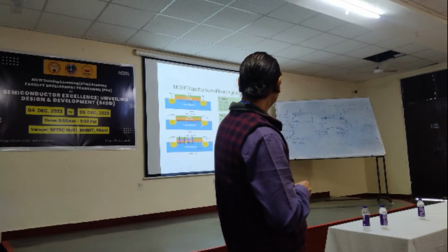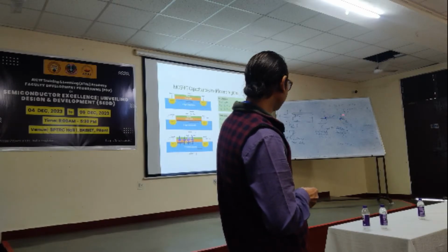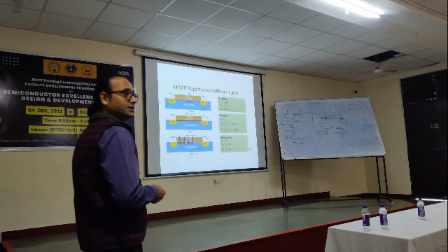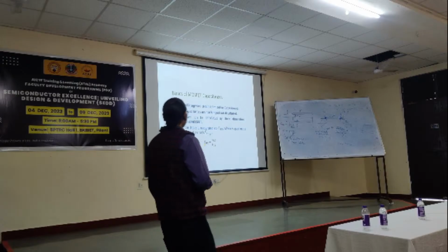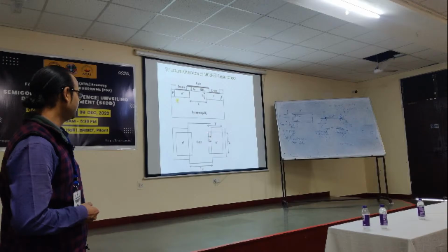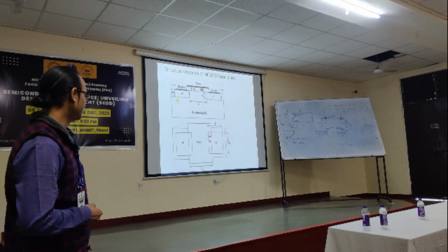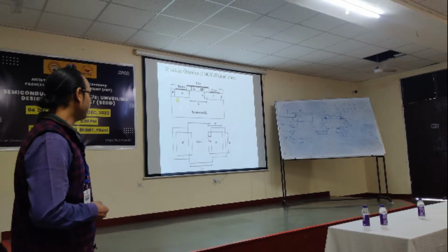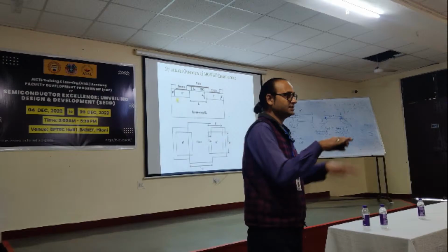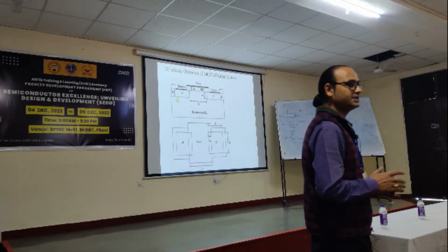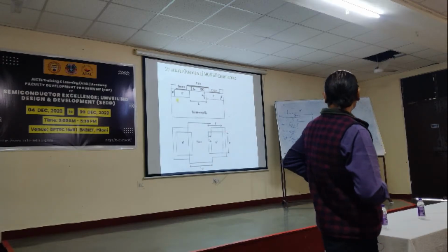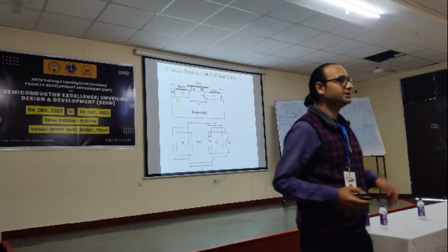The overlap part will remain there because it is directly below the gate, where the oxide is. Did you get it? And this LD I wanted to show is this overlap. So what will happen to the channel length in this case? If the channel length was LG earlier, and because of fabrication mismatch there is an overlap of LD, what will the channel length be now?